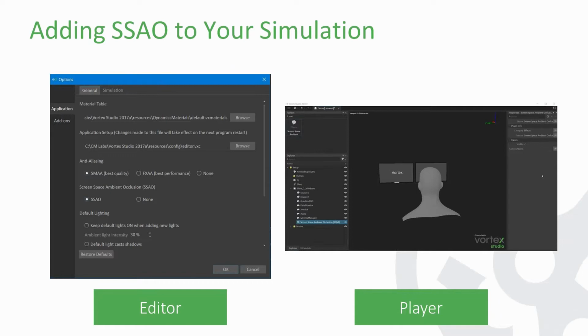And Marc-Alexandre, you've already mentioned that you can turn it on in the Vortex Studio editor in the options panel, which you can see right here. It's under the anti-aliasing setting. Now, with the player, it is a simple extension that you add in your setup document. That is correct? Yeah, exactly. In your setup editor, you just take the screen space ambient occlusion and drag it to your configuration panel. In the editor, it's already available as an option so that you don't have to go through that additional step while you're working.